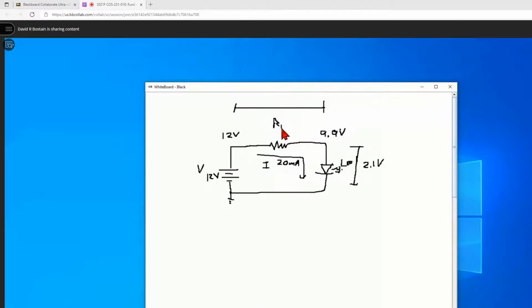All right, now, what's the voltage drop? You divide the 9.9 by the 0.02. Well, no, we can't do that because the voltage here across the resistor goes from 12 down to 9. What we need to know is what is that distance? What's that voltage difference? You just subtract the two numbers. Okay, so what number is it? 2.1. Okay, so if it's 2.1 to get to here, and then it's 2.1 to get to here, doesn't there seem like there's something wrong?